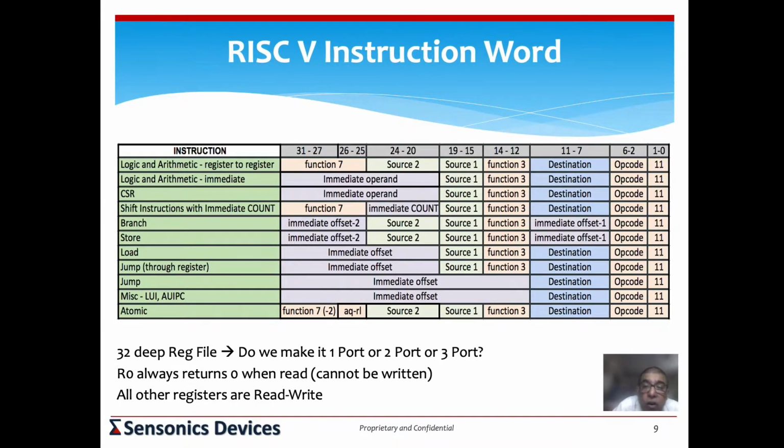And as you can see here, once you've structured it like this, this looks very, very elegant. We are not talking, by the way, about the actual bit patterns, but you need to. Whenever I start a design, I actually make an Excel sheet and put all the actual bit patterns there. We will need the bit patterns for the actual design when we're decoding. So the first thing to do is to put that in. But another useful thing to do is to summarize it in this form, because this will let us create a first draft of our data path.